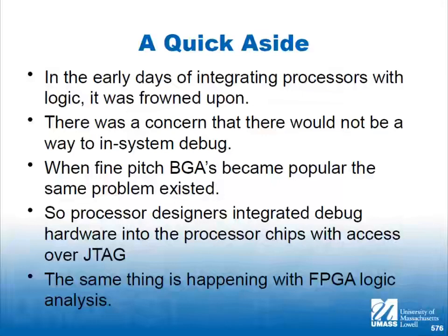So right around that time, the microprocessor manufacturers were seeing the same thing. So what they started doing is putting a debug port on the processor. And the electronics of that thing that senses breakpoints, the thing that allows you to interrogate the processor and change it, they just put right in the processor. Because as the processors got bigger and bigger, that stuff stayed about the same size. So it became significantly less of a burden on the total size of the chip.